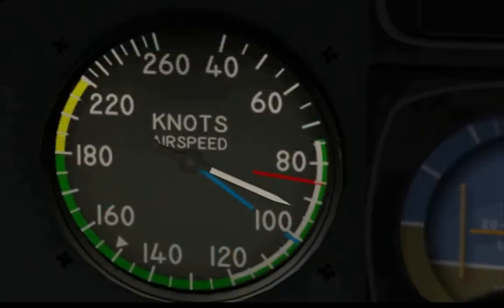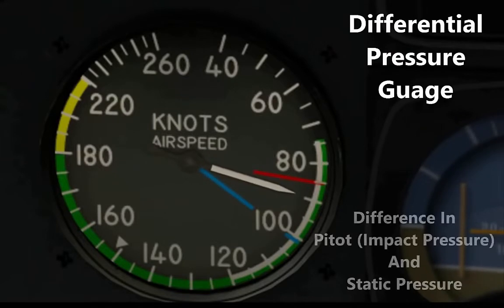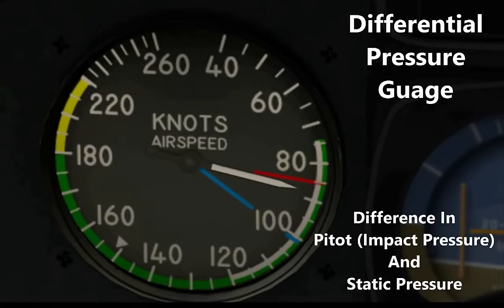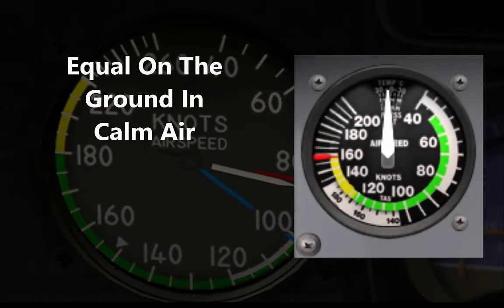The ASI, shown above, is a sensitive differential pressure gauge which measures and promptly indicates the difference between pitot, impact or dynamic pressure, and static pressure. These two pressures are equal when the aircraft is parked on the ground in calm air.